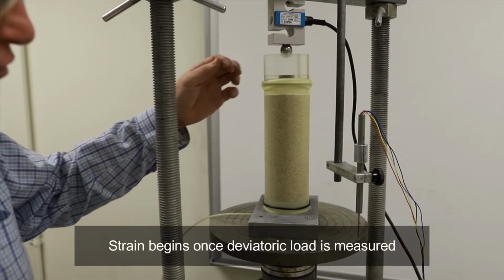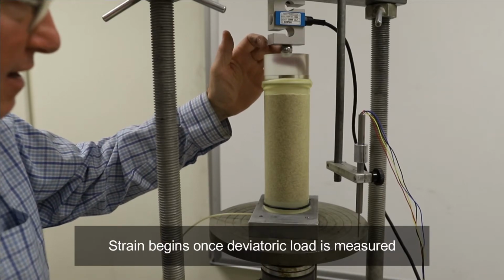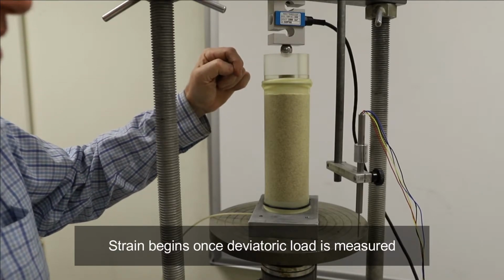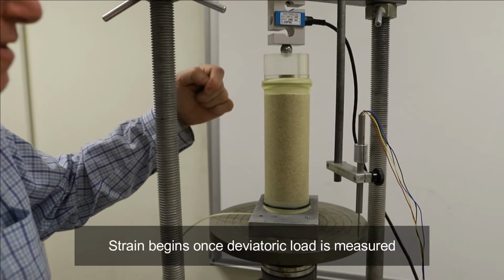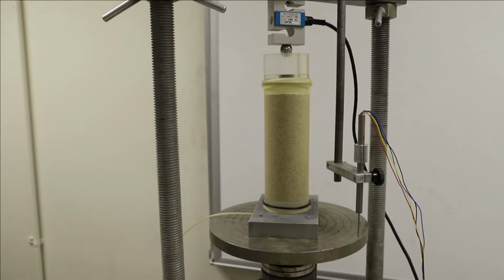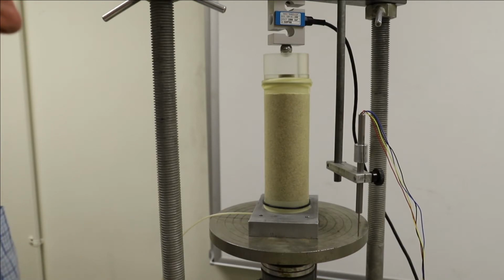So these first initial readings in the data file don't correspond to strain. We don't calculate strain as starting until we have contact in the system and we're getting deviatoric stresses due to this deviatoric load, right? Now we have contact. So we're rolling and acquiring data twice per second. We're measuring again the deviatoric load and the LVDT. Since this test is going to go on for about 10 minutes, I'm not going to film the whole thing, but we'll shut it down for now and bring it back when you can see the deformed shape.